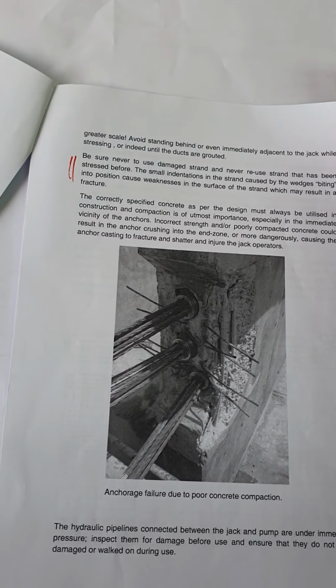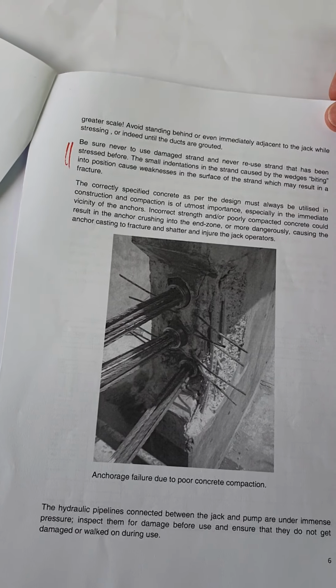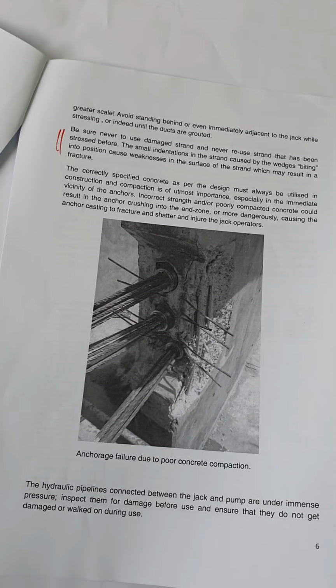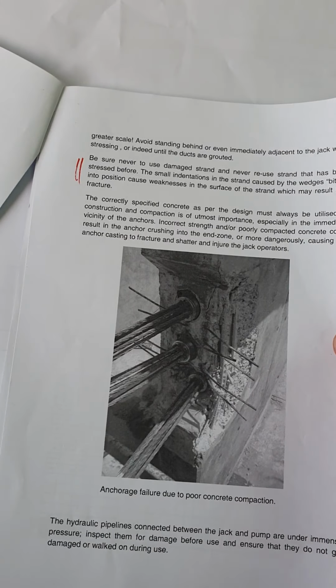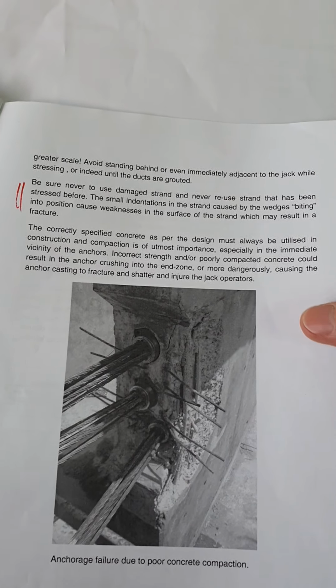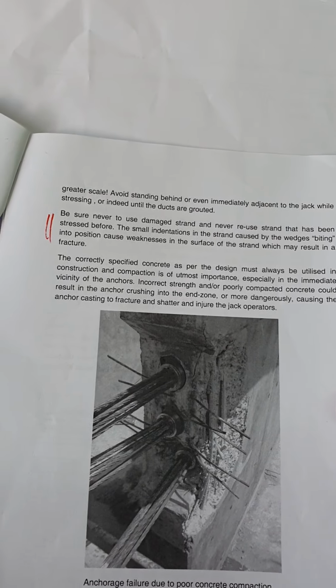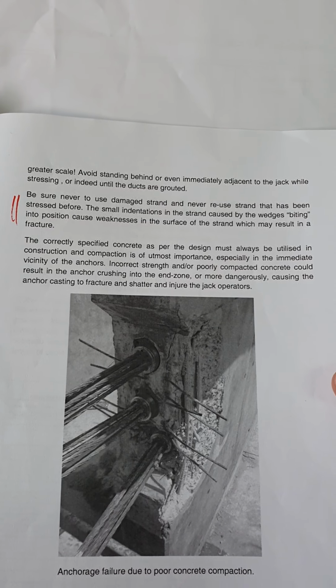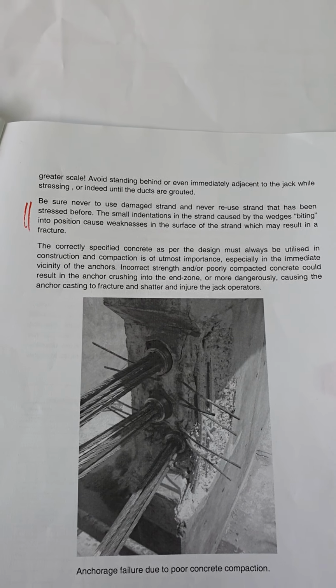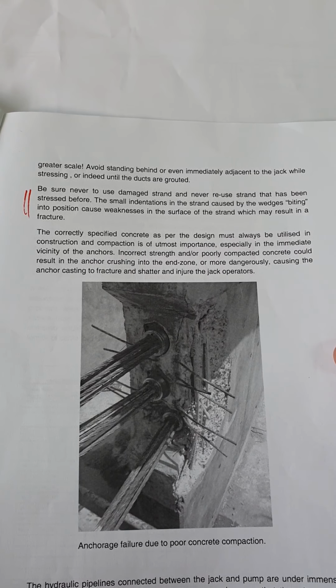Very dangerous. Don't ever stand immediately adjacent to a jack while stressing, and never behind the jack. Never use damaged strand, never reuse strand. Small indentations in the strand are left behind from where the wedges have bitten into the steel, and that causes a weakness in the steel, so never reuse the strand.